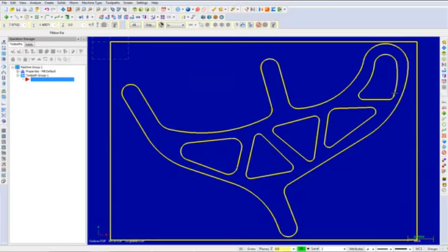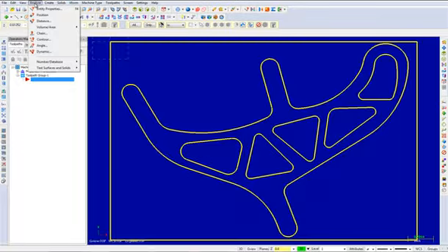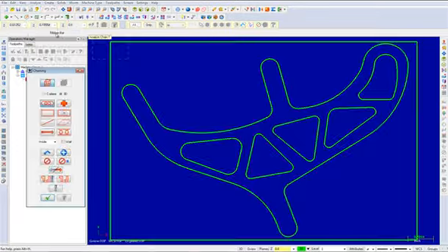We will now analyze the chain. Specifically, in this step you will use Analyze Chain to check the chains and fix them using Trim to Entities. Select Analyze Chain. Leave the chaining dialog box set to Chain. From here, select the outside profile as shown.